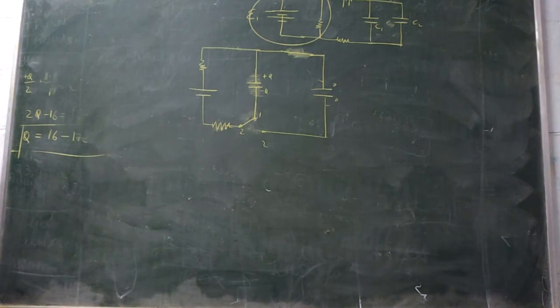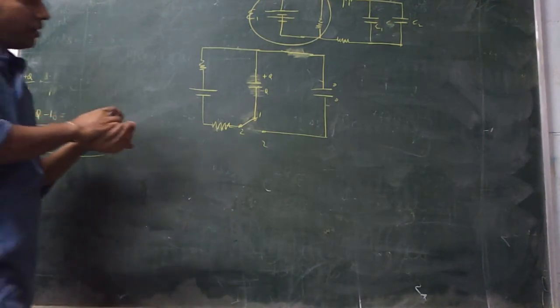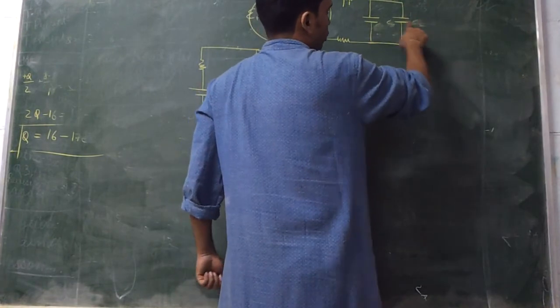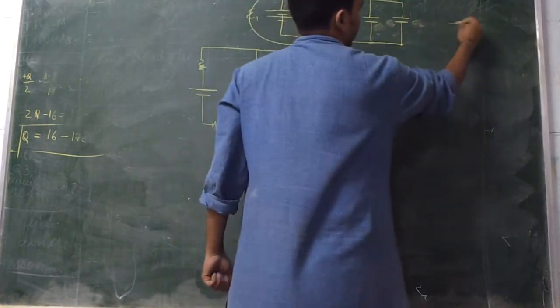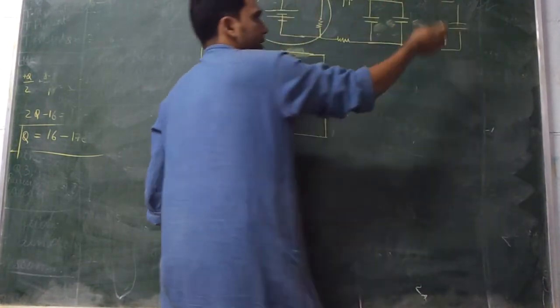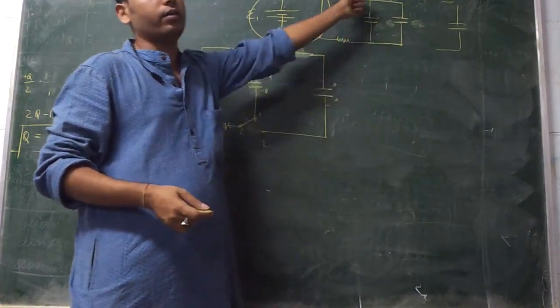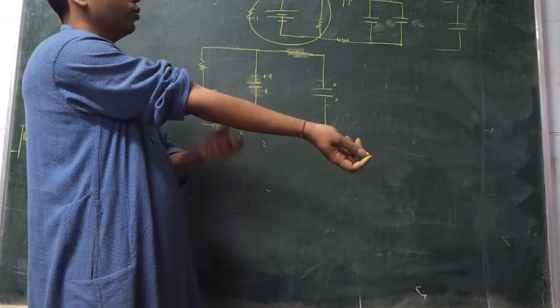Again, if they are initially charged, you will have to find the initial condition of the capacitor. As a single capacitor, what is the condition? When you have two capacitors like this, say let me give you a value. Both were discharged, then you can obviously make it a single capacitor and solve the circuit. And when they ask you what is the charge on one of these, you equate the voltages and you can get the charge ratio on the two.